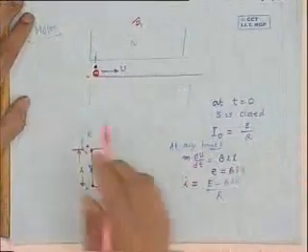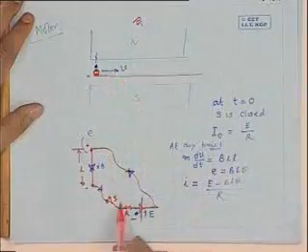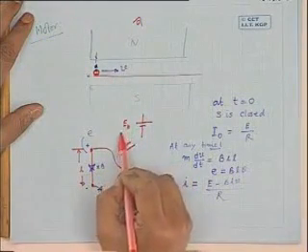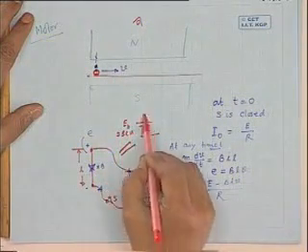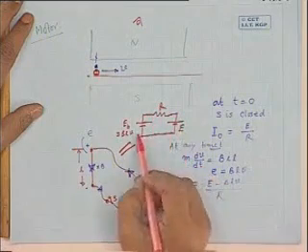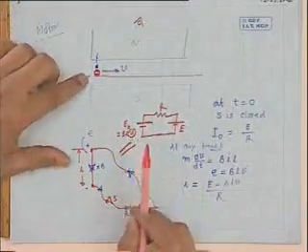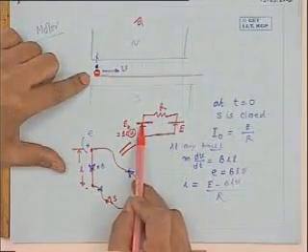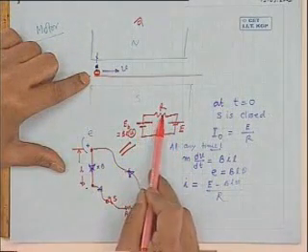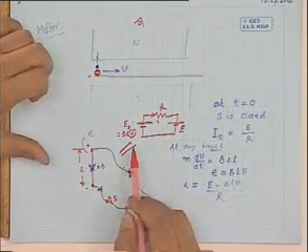Current will become 0. In fact, that is what it should be. Because once the conductor starts moving from left to right, velocity is increasing. So this circuit is equivalent to a back EMF, EB, which is equal to BLV, and here is your R, and there is the supply voltage E. So this battery EMF is a function of velocity, initially 0. Now as it moves up, this battery EMF keeps increasing. Current is this minus this by R. So the current will start falling.